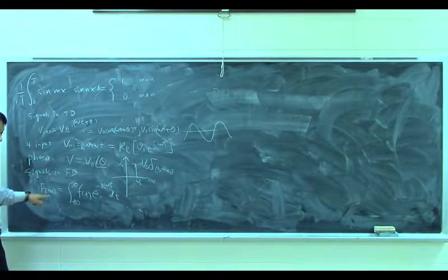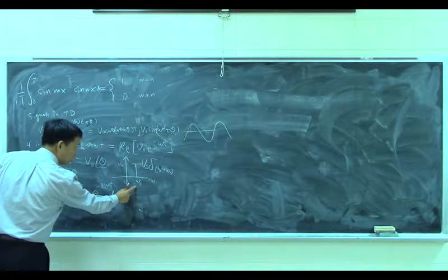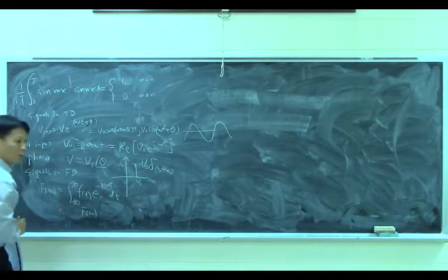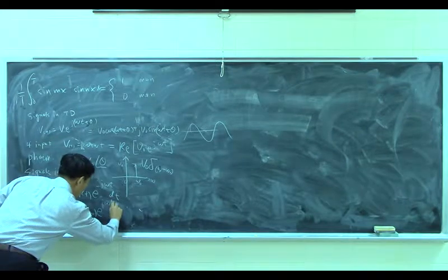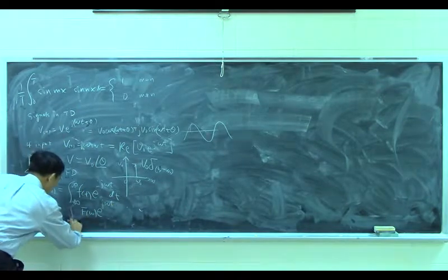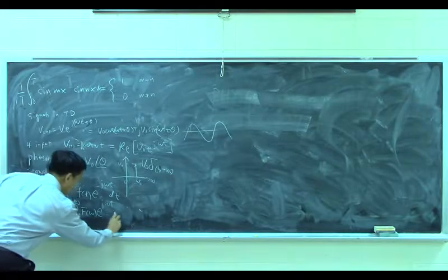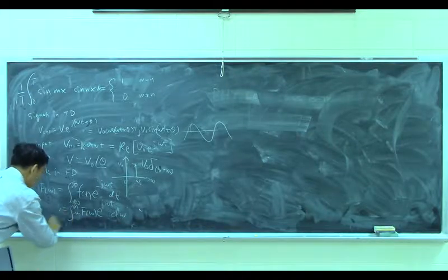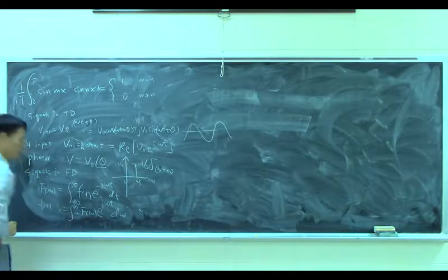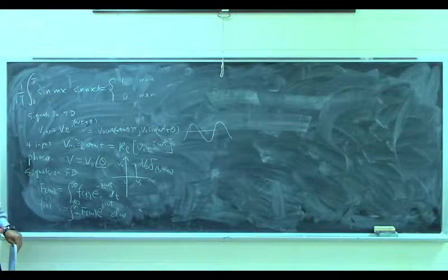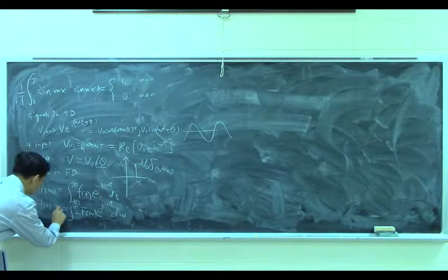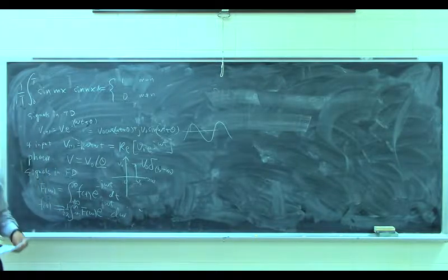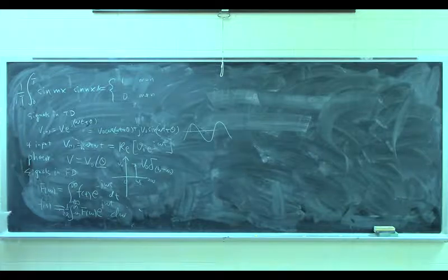Similarly, if we are given this frequency domain signal and want to obtain f(t), we multiply by e to the j omega t, and integrate again over all frequencies with respect to the frequency. This will give us f(t) mathematically. But for some reason, we are going to divide it by 2 pi to make this consistent. So we divide by 2 pi here.